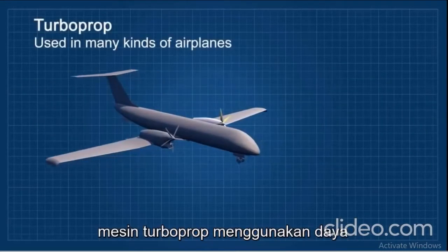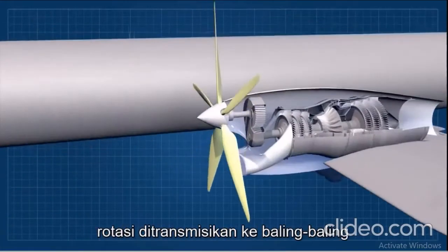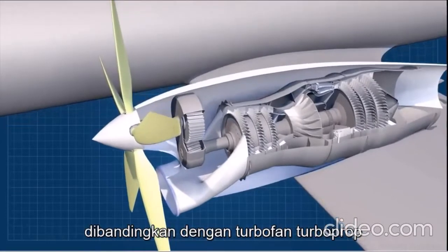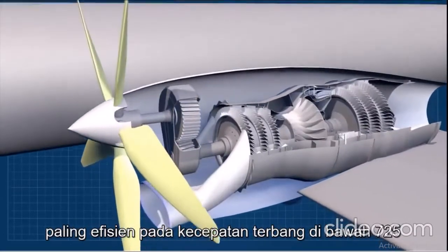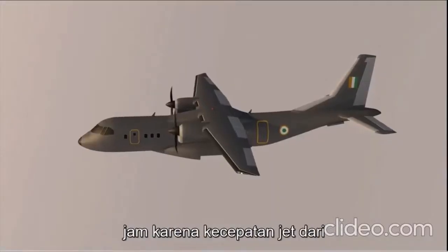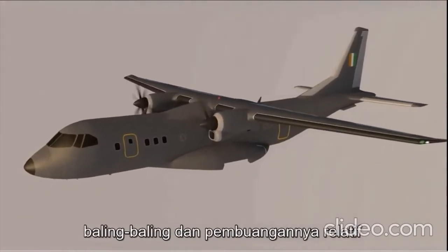The turboprop engine uses the power from the turbine, and through a gearbox the rotation is transmitted to the propeller. Compared to turbofans, turboprops are most efficient at flight speeds below 725 km per hour or 450 miles per hour, because the jet velocity of the propeller and the exhaust is relatively low.